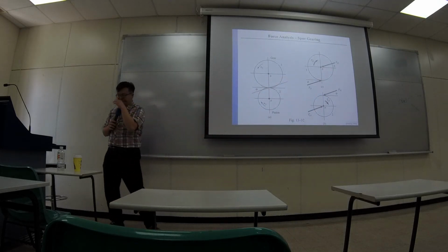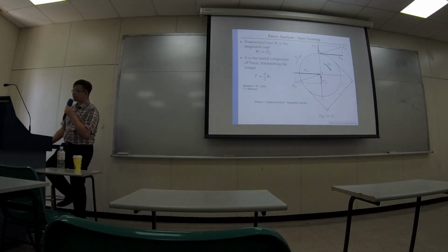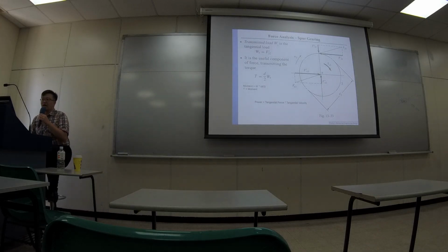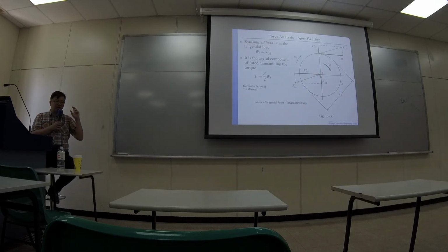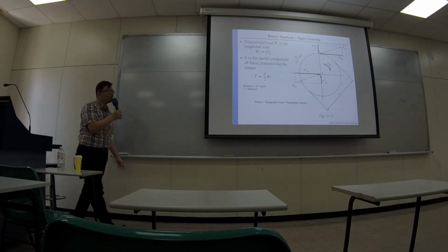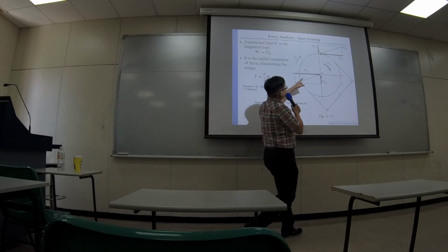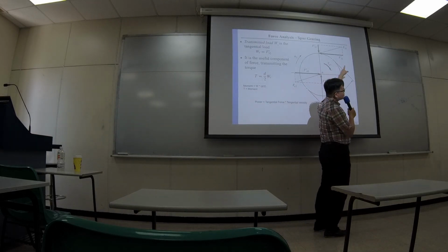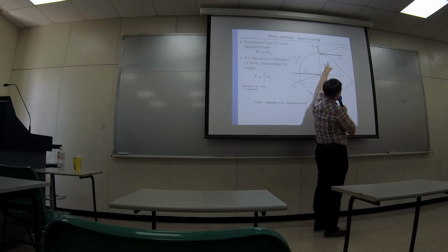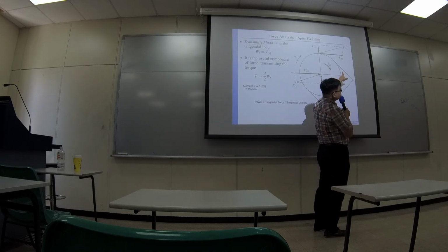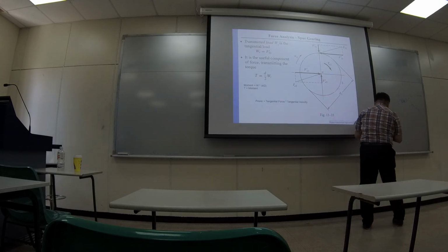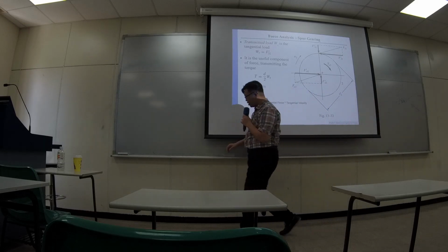Opposite direction. Okay. Now, later on, when we focus on the force that is applied to the teeth, the most important part is actually the transverse component of that F32. So F32 transverse will be applied to your teeth.